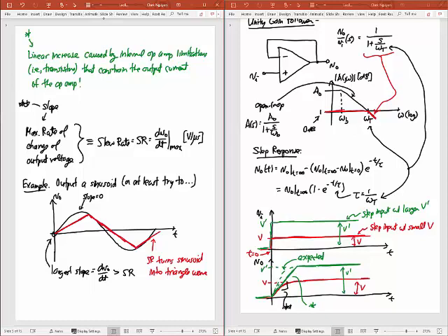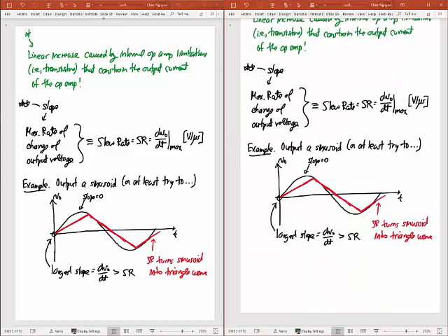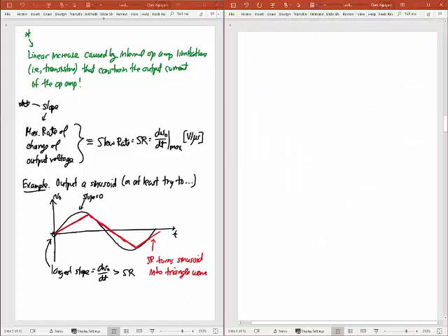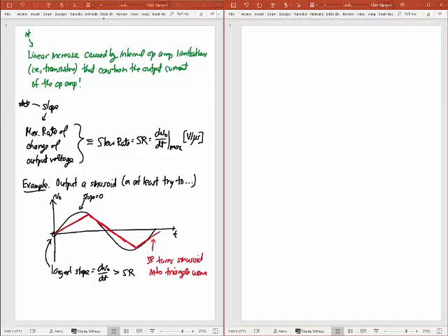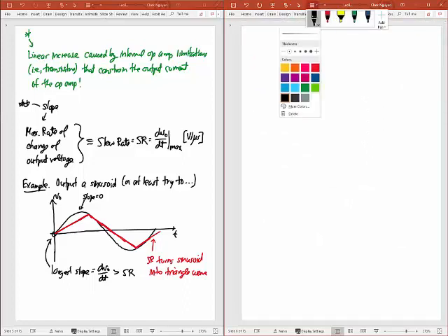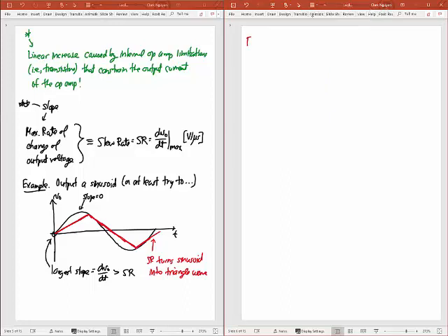Okay, so there's a lot of things that can affect what this op-amp is putting out when you think of a practical op-amp. And so because a lot of times you want to make sure you have a sinusoid, this is why people define something else, which is not an op-amp non-ideality, but is sort of a parameter associated with one, and that's the full power bandwidth.